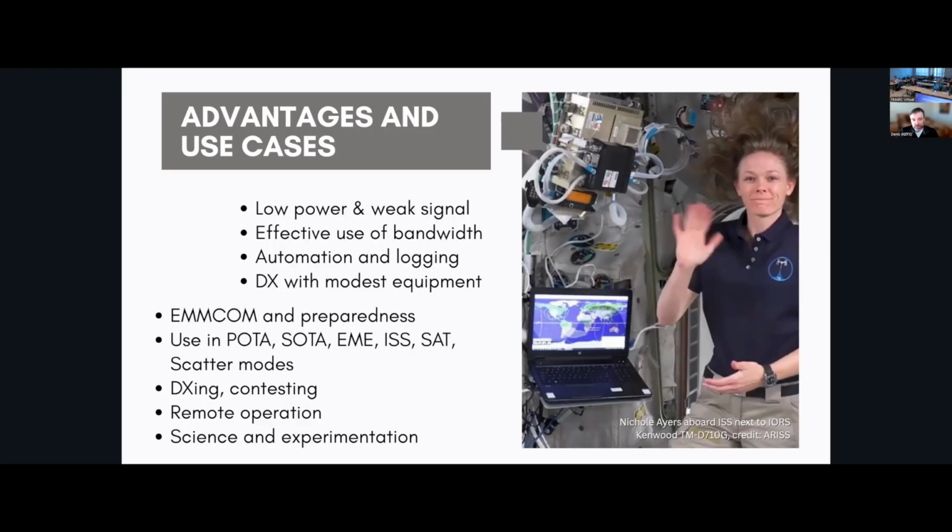For example, one of the very popular digital modes, FT8, uses sub 3 kilohertz bandwidth, the regular voice channel, and there can be 50 stations packed into the same channel that normally would be several operators just running pile ups. Here you can hear clearly dozens and dozens of stations just within the single audio channel.